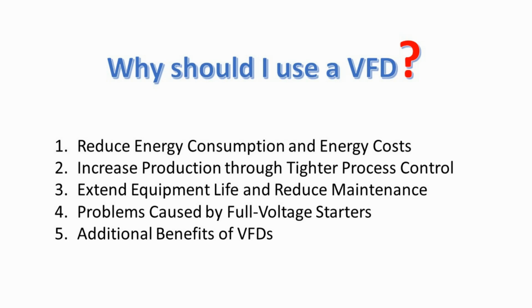Eliminating throttling valves and dampers also does away with maintaining these devices and all associated controls. A soft starter for the motor is no longer required. Controlled ramp-up speed in a liquid system can eliminate water hammer problems. The ability of a VFD to limit torque to a user-selected level can protect driven equipment that cannot tolerate excessive torque.